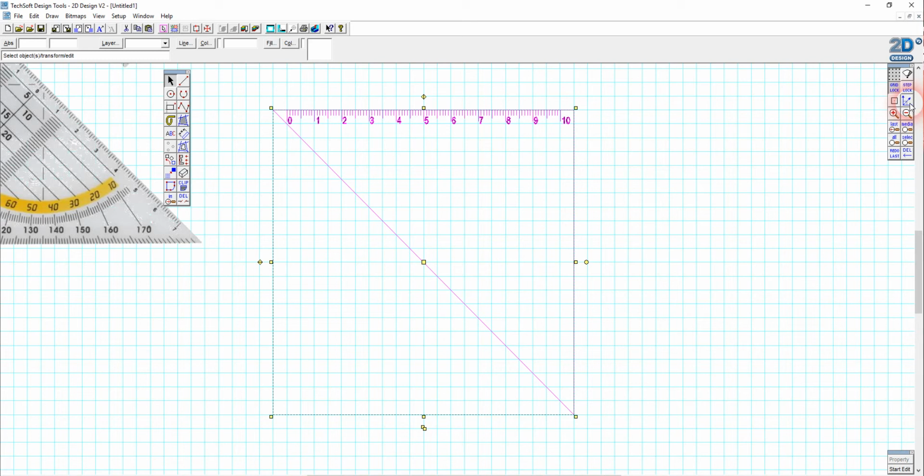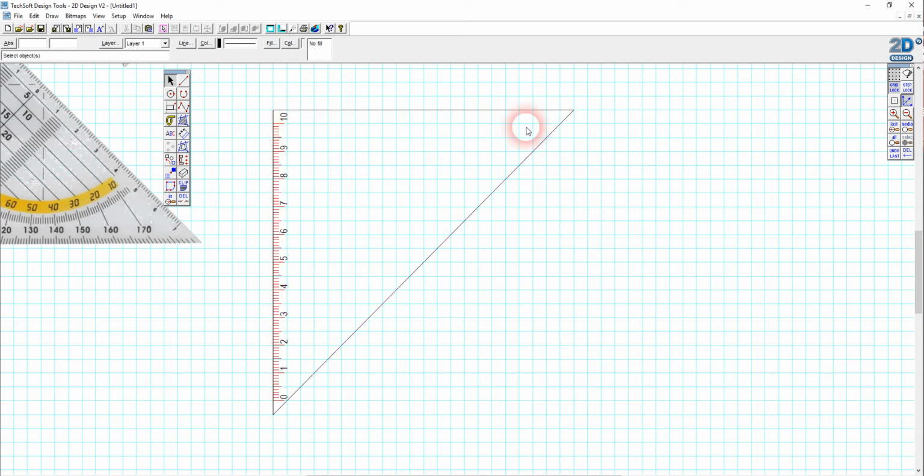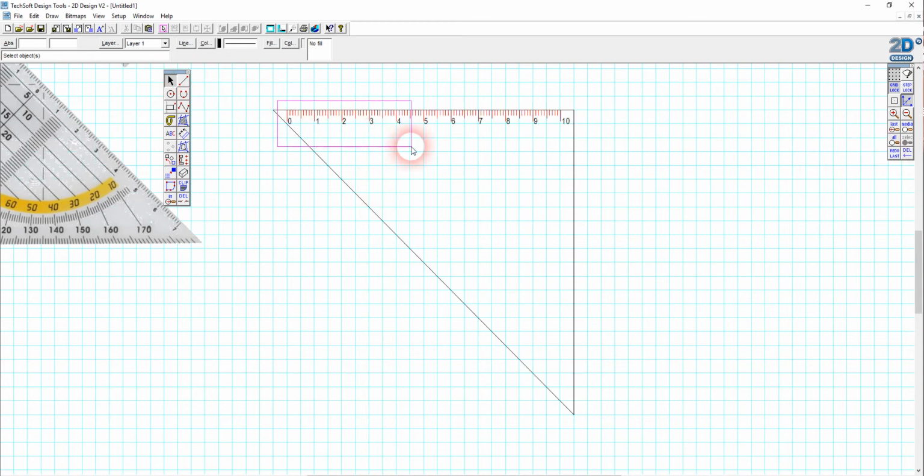And I know that because if I right click on this button, I can see here it says radial lock on, step angle 45. So now with the radial lock turned on, if I click on this little rotation tool, click move, you see how it locks there to 45 degrees, 90 degrees, and now I've got this edge to work to right here. Well, you know what I'm going to do to make my life easy? I'm going to take that, copy, Control C, paste, Control V.